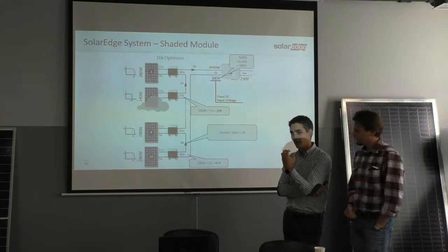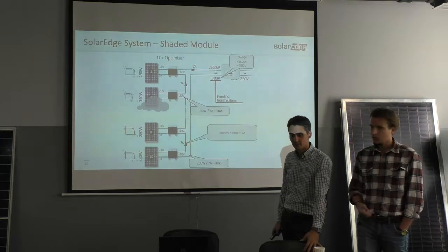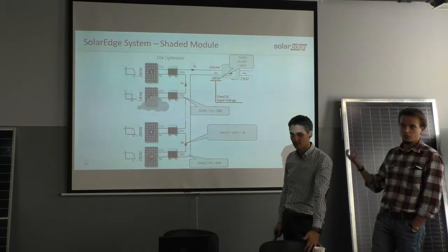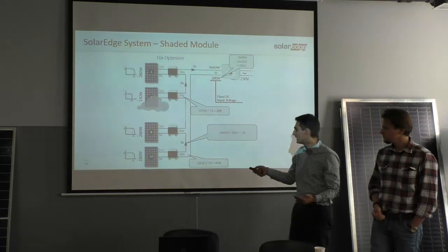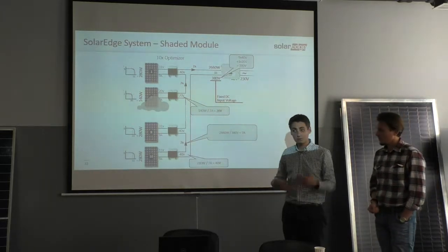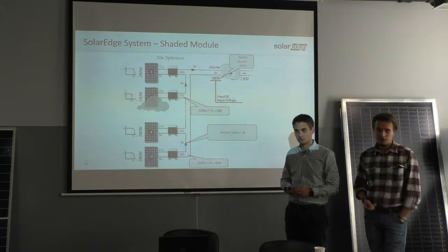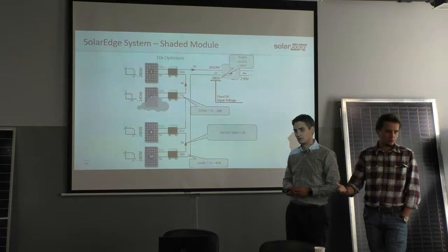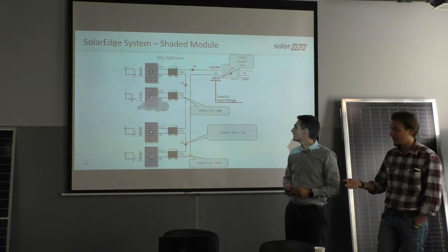We have to take into account that in this case the bypass diode in one module reacted. It's a big difference. If modules work like this, say, 50% of the day, we are talking about 30% of difference. That is a lot, because if several modules are in shade, the conditions change.